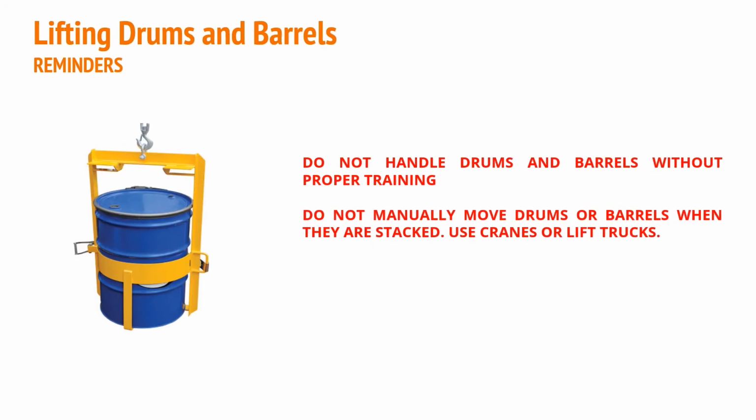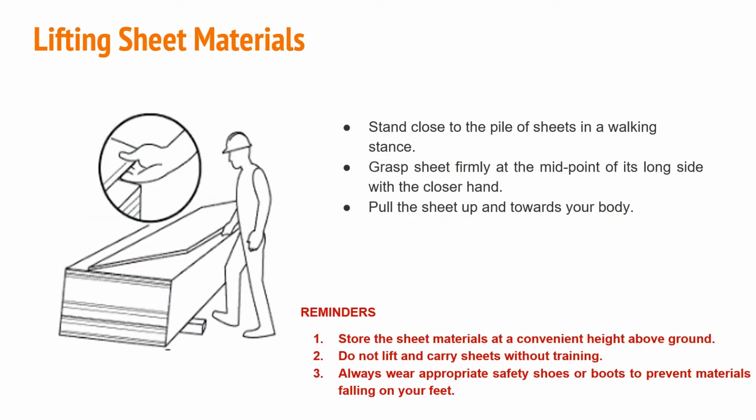Important reminders in lifting drums and barrels, which should always be followed: do not handle drums and barrels without proper training. Do not manually move drums or barrels when they are stacked. Use a crane or lift trucks. Next is lifting sheet materials. Before starting, make sure to keep in mind these reminders. First, store the sheet materials at a convenient height above ground. Do not lift and carry sheets without training. Always wear appropriate safety shoes or boots to prevent materials falling on your feet.